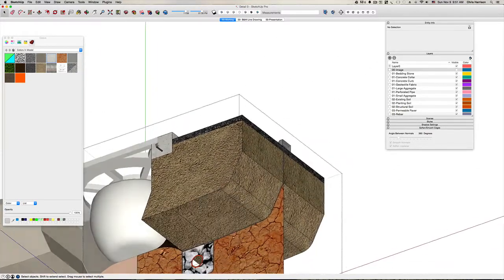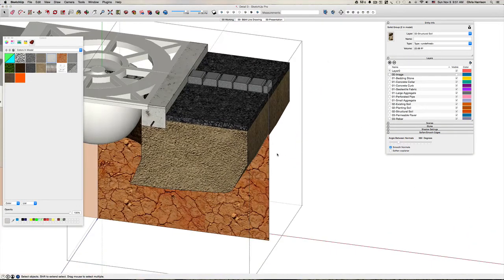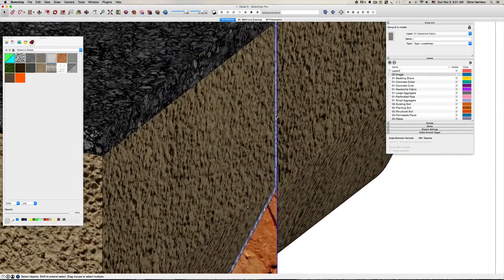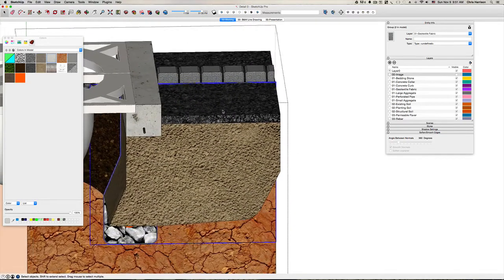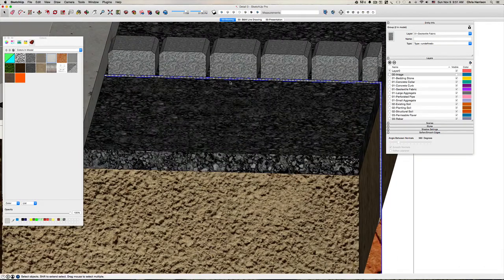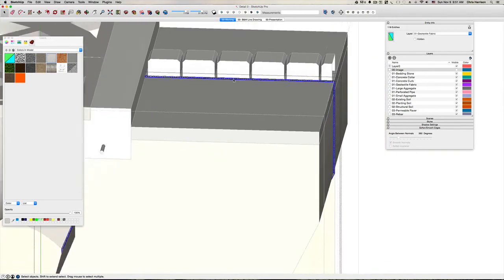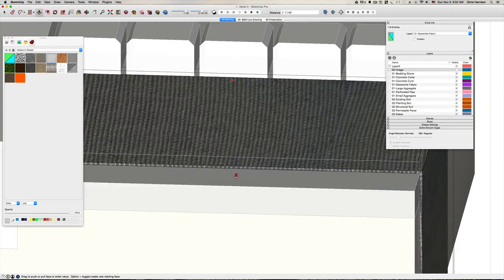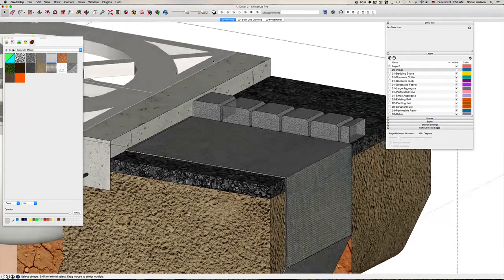And now I need that fabric that's going to wrap this too. I'm also going to click on this and just soften the edges too. I just like keeping all that clean. And again, we need to do that sweep here as well. Same thing. So I'm going to double click here. Wrong one. Double click here, and just extend this out. Maybe we won't extend it out the entire way. We'll just show some of that right there like that.